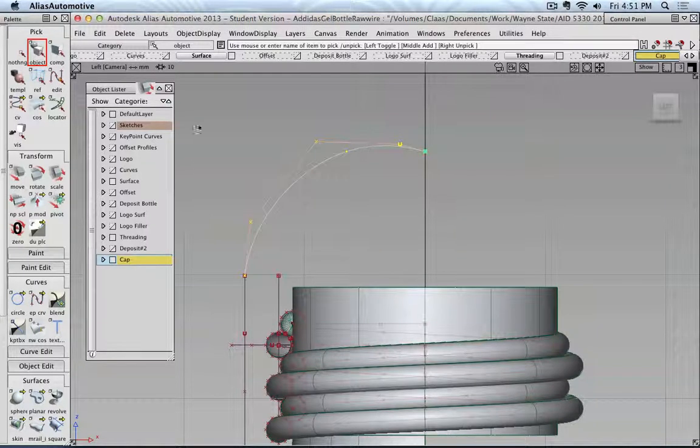Okay, I actually used the wrong curve tool this time, so I have to go to the CV. So alt click with left mouse button, middle mouse button, drag it out, and then left mouse button so it fits onto this point. That is good. And then I could maybe go into the CV edit mode, select this CV, middle mouse button, move it left and right, and then snap it to this point. So I drag this line out, being somewhat G1 continuity.